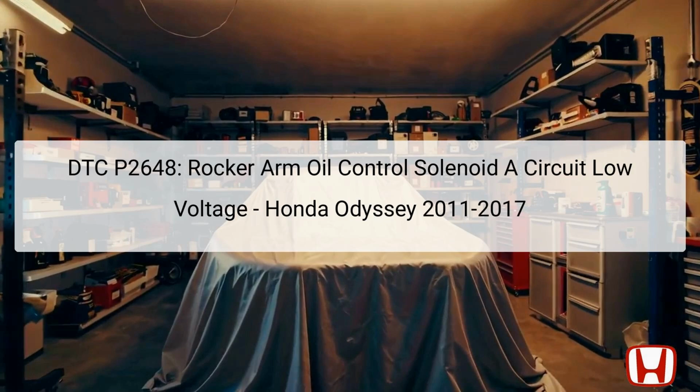Located in the engine bay, the rocker arm oil control solenoid manages the oil flow to the rocker arms, which is crucial for variable valve timing performance. When voltage is inadequate, it can lead to engine performance problems, triggering this DTC.